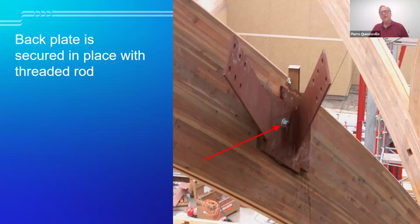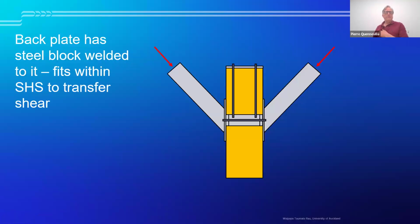So the back plate was secured with the threaded rods, and we can see also a plate at the top of the member. The back plate has a steel block welded to it, and it fits within the SHS to transfer the shear.